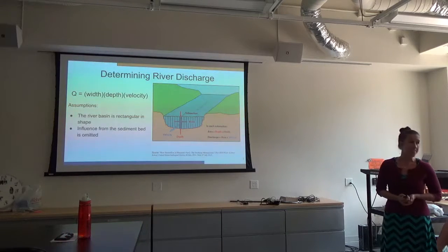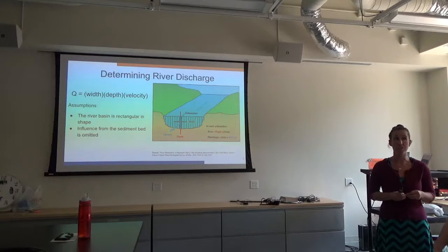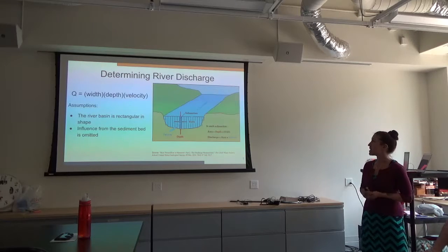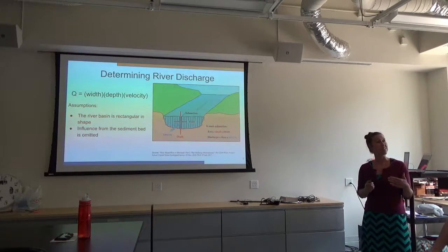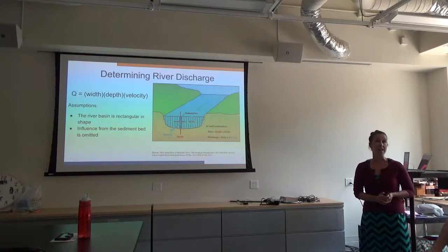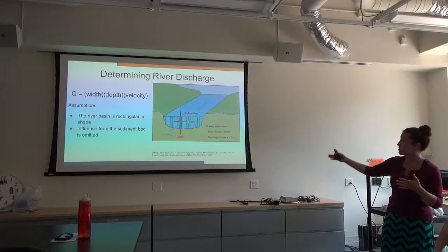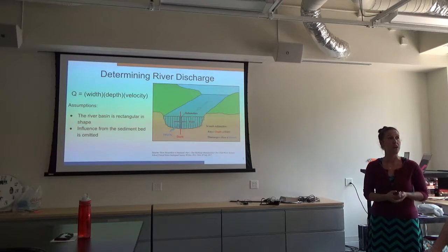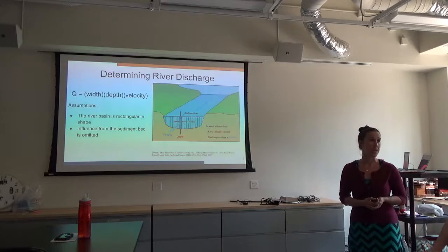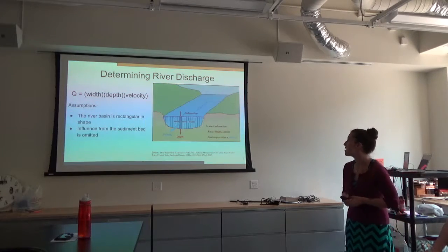To determine the discharge of the river, I focused on one cross section of the river, mostly at Riverview Park. To do this, I needed to determine the width, the depth, and the actual velocity for that particular cross section. I segmented out the depth values so that you can see the subsections are useful in not only generating a mean value for the depth, but also helping to determine how the stream power is segmented into each of those smaller sections.